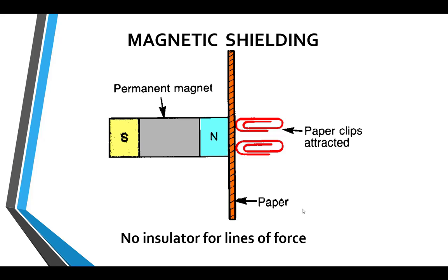And the conductor can be stationary. In fact, this is what happens with an antenna. The antenna is a conductor that's stationary. The radio station sends out its signal as electromagnetic waves. Those waves or lines of flux cut across that stationary conductor, the antenna. That induces a voltage in that antenna, and that becomes your signal, and that voltage is sent to the rest of the radio and processed through tuning and filtering and volume and things like that, and ultimately goes to a speaker to where you can hear it.